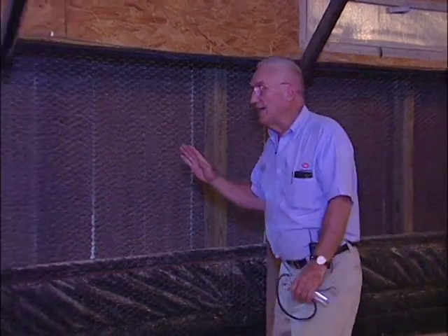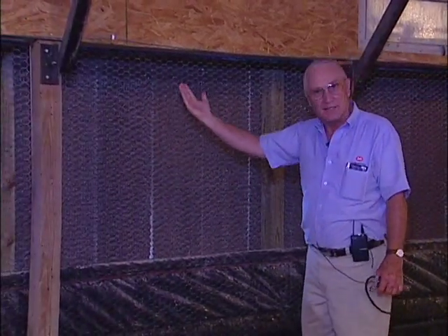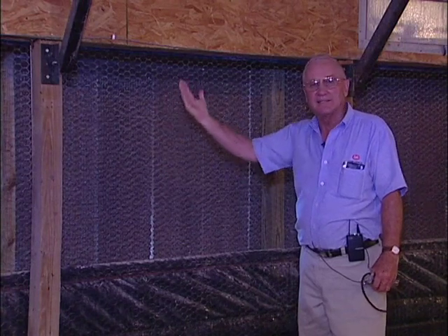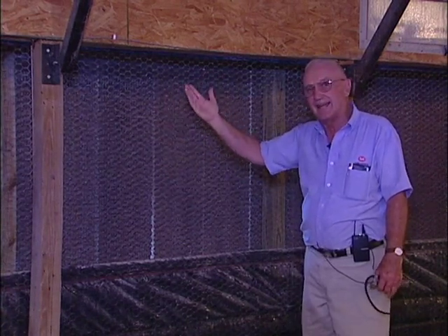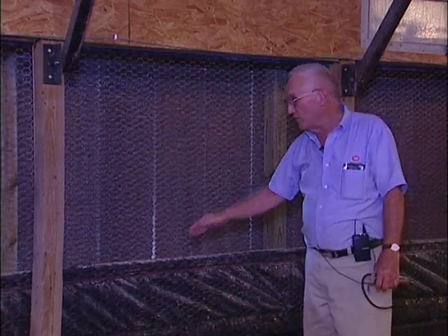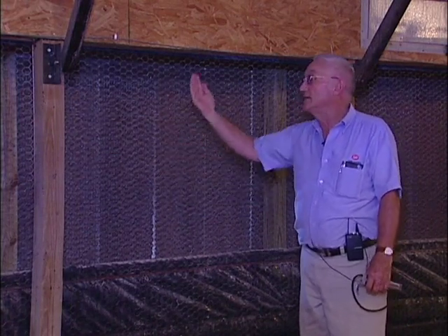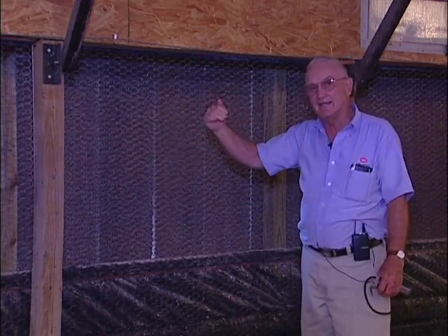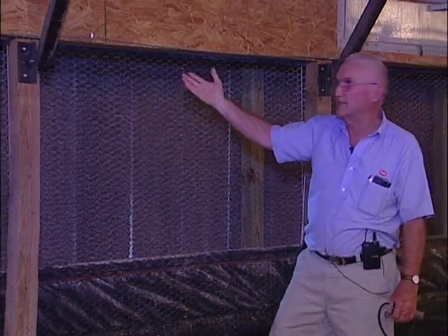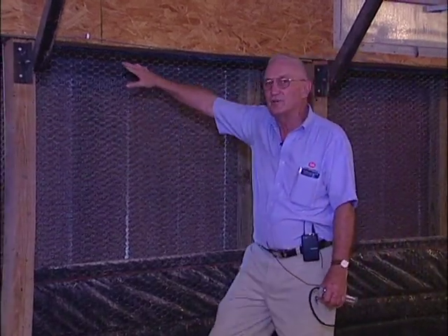And the reason for that is up here in the top of this vestibule, the air is extremely hot because it's outside. And if the air comes up between this curtain and the pads and goes up and comes back in the house, it actually increases the temperature that you've dropped through the pad.